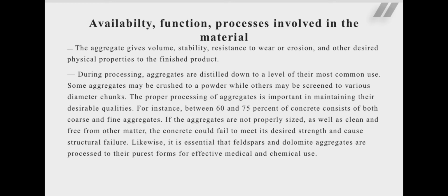The aggregate gives volume stability, resistance to wear or erosion, and other desired physical properties of the finished product. During processing, aggregates are reduced down to a level of their most common use. Some aggregates may be crushed to a powder, while others may be screened to various diameter chunks. The proper processing of aggregate is most important in maintaining their desirable qualities.